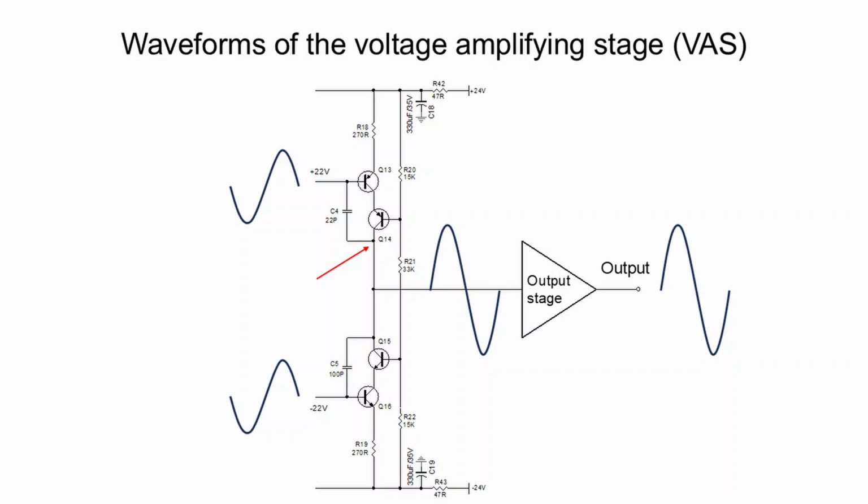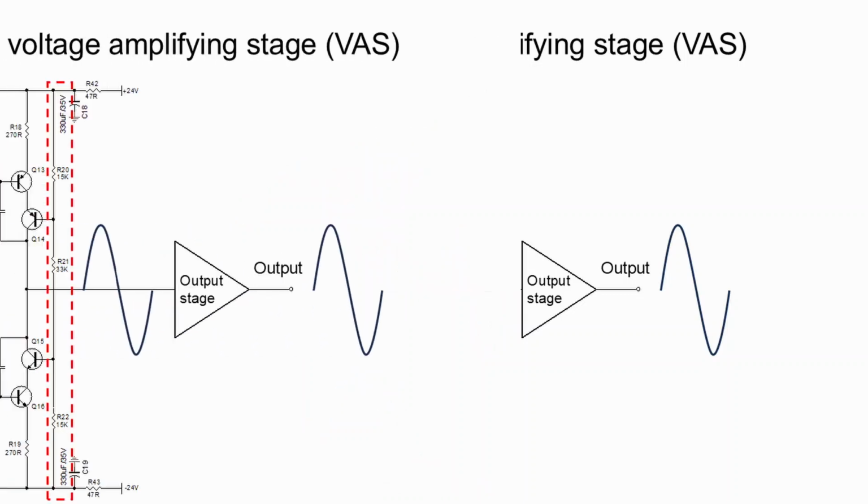In the cascode amplifier formed by transistors Q13 and Q14, the output is produced from the collector of transistor Q14. And the load seen by transistor Q14 is the collector of transistor Q15. Similarly, the impedance from the collector of transistor Q14 is the load for transistor Q15. Since impedance from the collector of a BJT is high, the cascode amplifier produces a very high voltage gain.